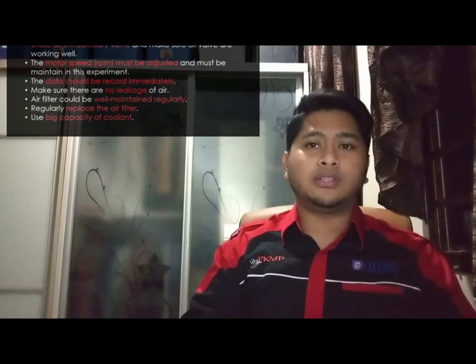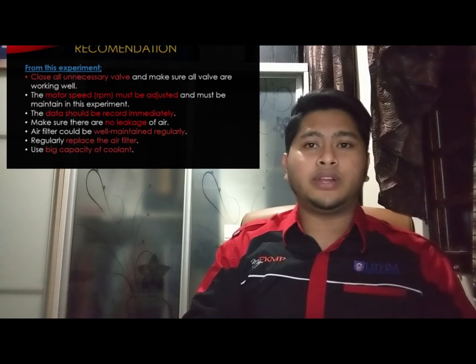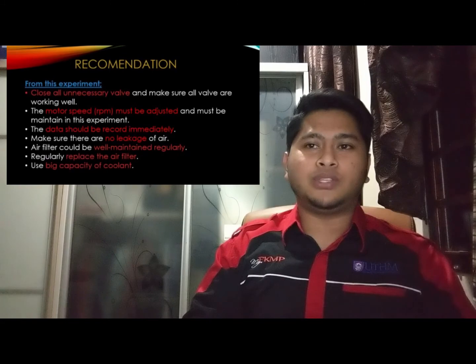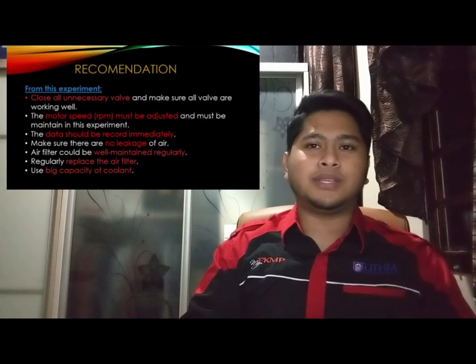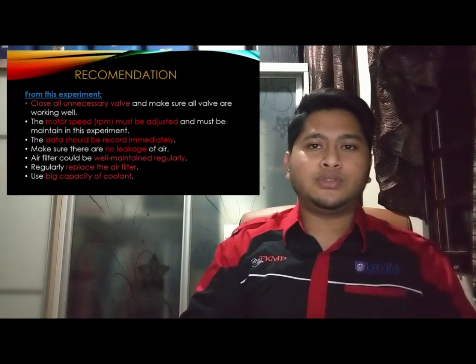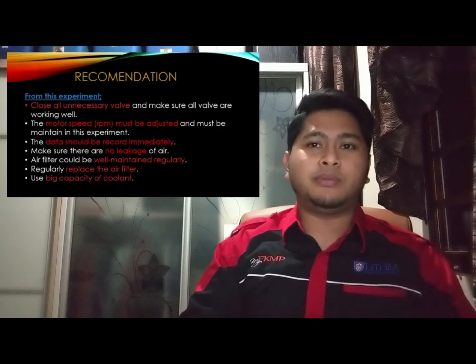As for recommendation, there are a few things that we need to improve to get a better result. Firstly, we should close all unnecessary valves and make sure all the valves are working well, because if a valve is broken, it can affect the flow rate of the air. Next, the motor speed, which is RPM, must be adjusted and maintained in this experiment. The data we should record immediately to prevent any misreading while the experiment is being conducted.